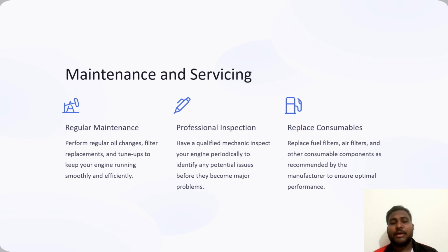Professional inspections: have a qualified mechanic inspect your engine periodically to identify potential issues before they become a major problem. Replacing consumable components like fuel filters and air filters as recommended by the manufacturer ensures optimum performance.